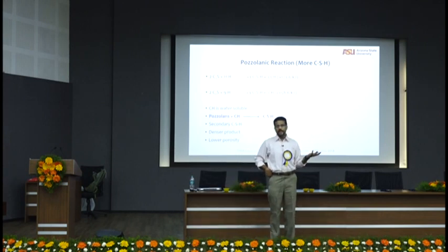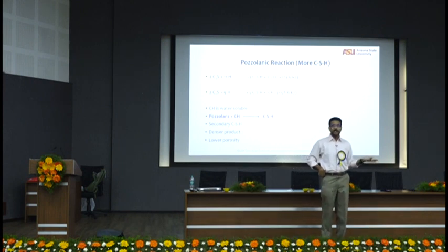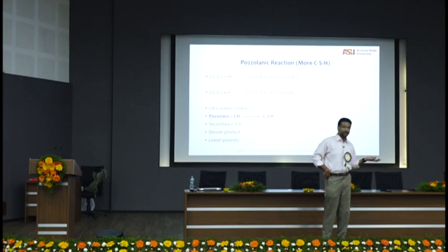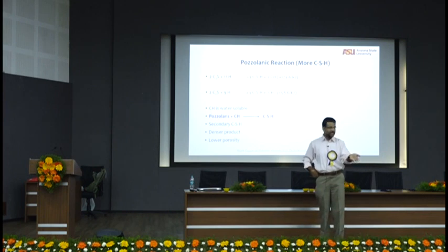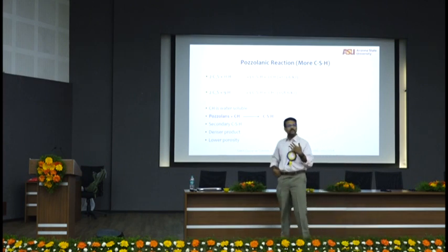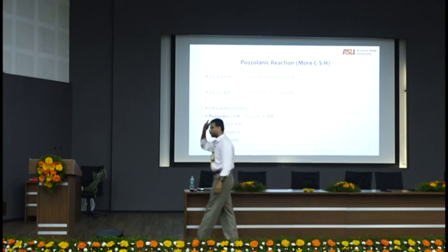3.15. General fly ash has a specific gravity of 2.4, 2.5, which means if I replace 15% of cement by fly ash, I am putting in more volume of fly ash, right? 15% by mass will end up to be 20% by volume, which means even if it doesn't react, forget it, your space is being filled. Just consider this as a cheap filler, non-reactive filler. I'll talk to you about the effect of fillers and the filler effect and what they do in these systems.